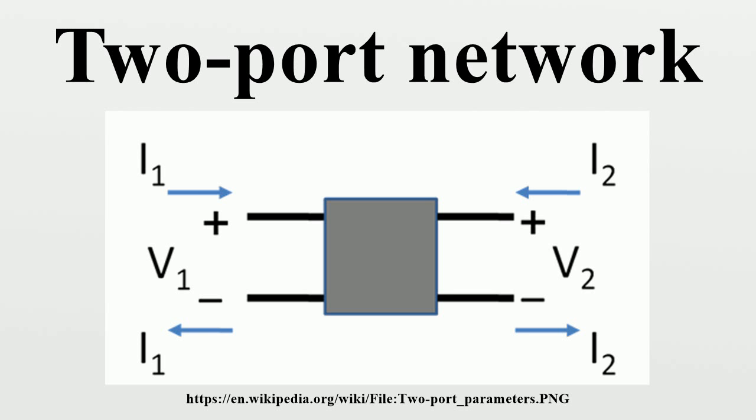is explained by observing that R1 of the lower two-port has been bypassed by the short circuit between two terminals of the output ports. This results in no current flowing through one terminal in each of the input ports of the two individual networks. Consequently, the port condition is broken for both the input ports of the original networks, since current is still able to flow into the other terminal.